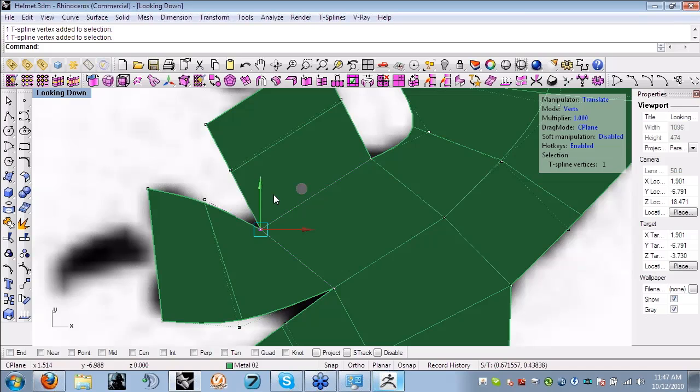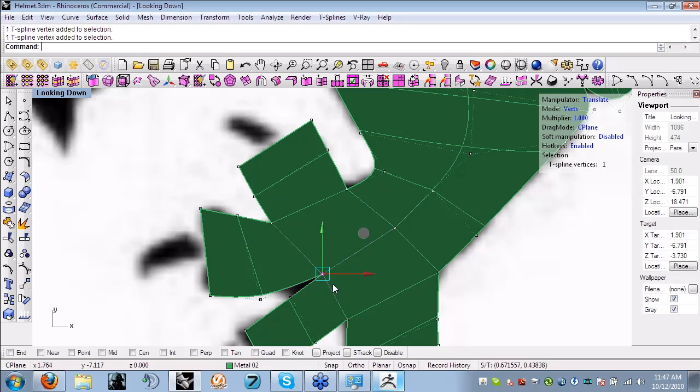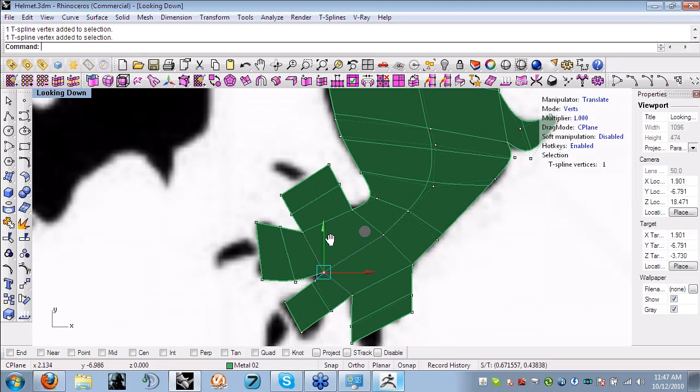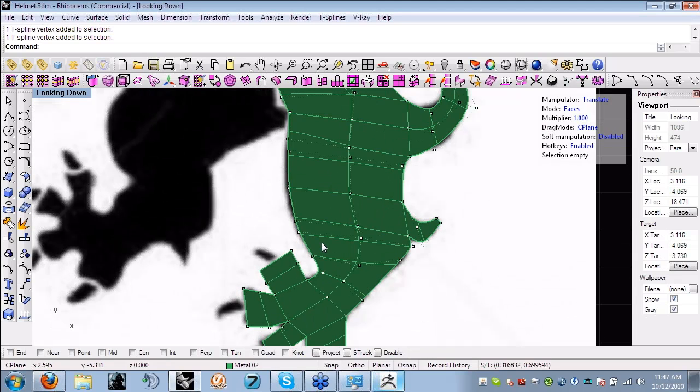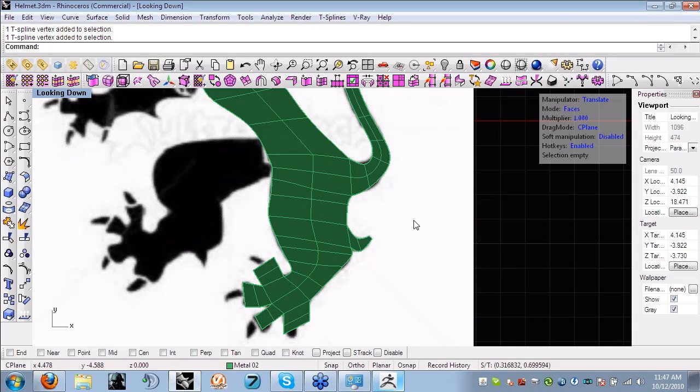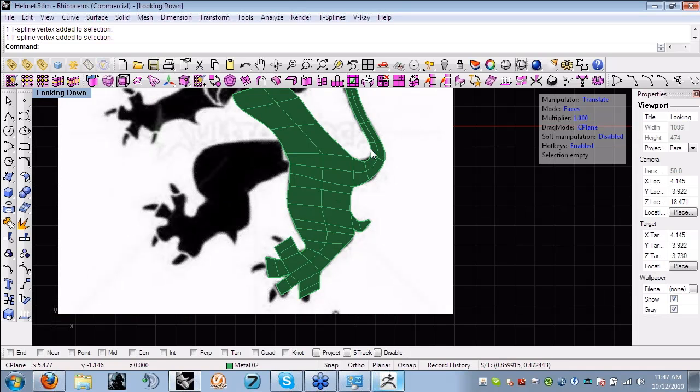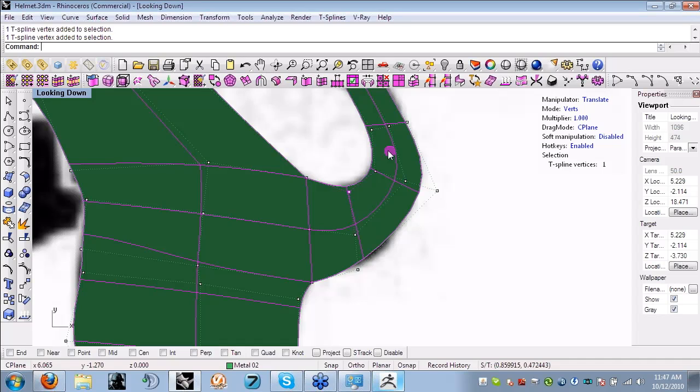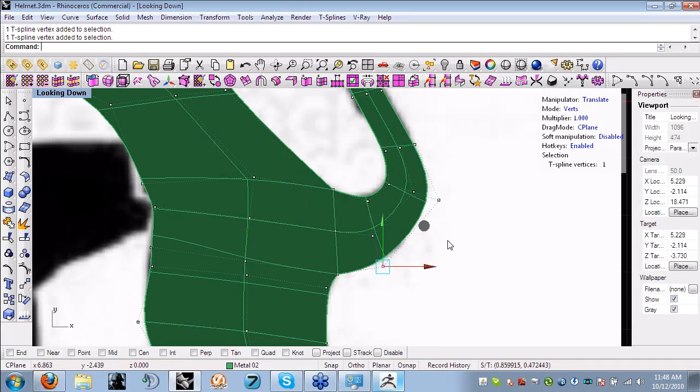I'm a firm believer that all signet style models should always be machined and never RP'd. So I don't worry about it with this particular model. If it is a problem, though, the nice thing is that T-Splines are always solids. So unless you turn the faces inside out or something, it's always going to be a nice, perfect solid that will have no trouble doing Boolean union or subtraction operations on.